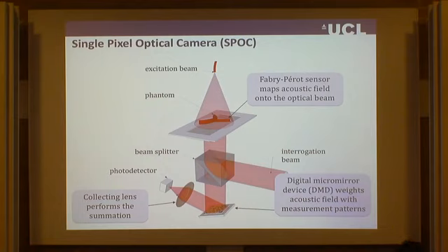If there are n pixels in the image, and the maximal value of each is between 0 and 1, then the dynamic range of measuring a pixel is 0 to 1, while the dynamic range of measuring n pixels is, of course, maximally n. So if this is followed by an 8-bit quantizer, this bites you. So this is a kind of inherent problem. The dynamic range blows up.